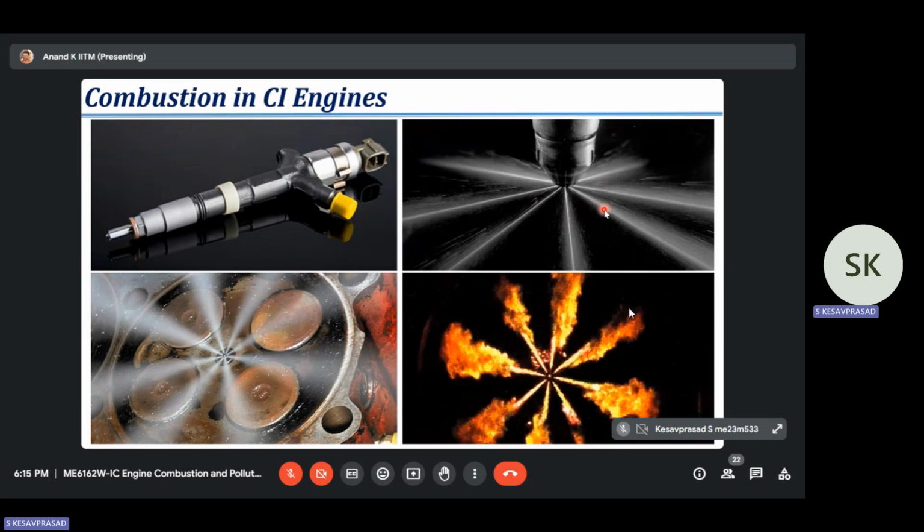You know that combustion is a gas-phase phenomenon. What you are introducing is initially liquid-phase fuel. This liquid-phase fuel has to get into gas phase, and then this gas-phase fuel has to mix with air in a finite proportion. Fuel and air cannot ignite at all possible proportions. It can ignite only at a finite proportion, which is called the ignitable range, which is again a property of the fuel. Fuel and air can burn only if mixed in a finite proportion.